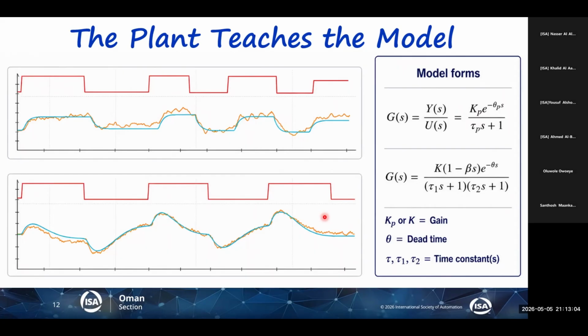I don't see the response everywhere in the unit. So it's really important to start early making the fit. Don't wait till the end of the day. You should observe all the anticipated controlled variables, all of them, and see a good response, so that you have data which you can use to build a model.